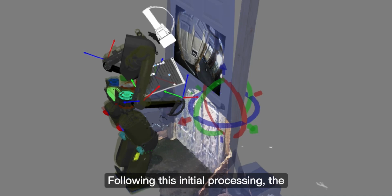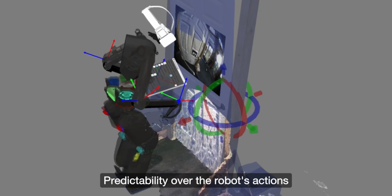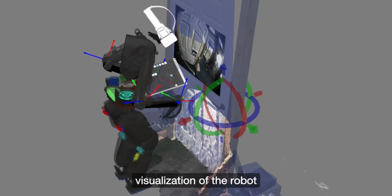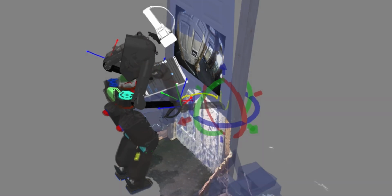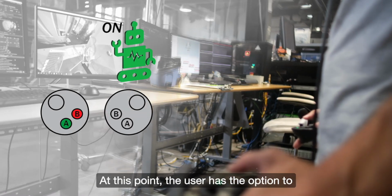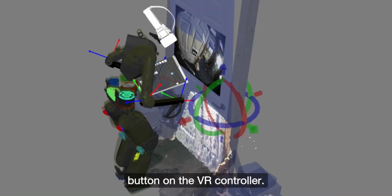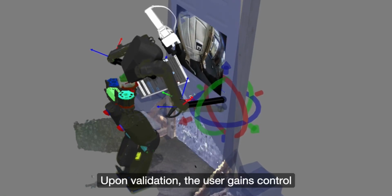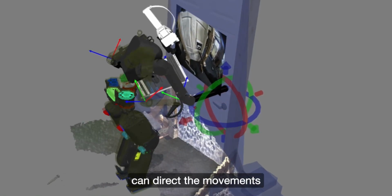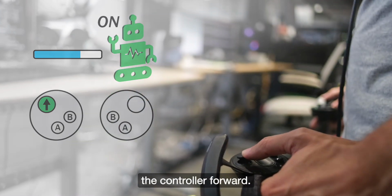Following this initial processing, the system presents a preview of the computed motion to the user. Predictability over the robot's actions is provided through a visualization of the robot with a gray ghost preview and spline trajectories. At this point, the user has the option to either accept or reject the suggested motion by pressing a dedicated button on the VR controller. Upon validation, the user gains control over the robot and can direct the movements along the computed trajectories by tilting the joystick of the controller forward.